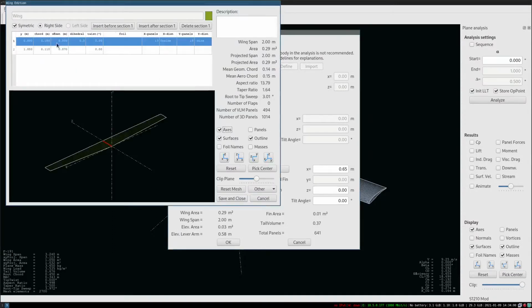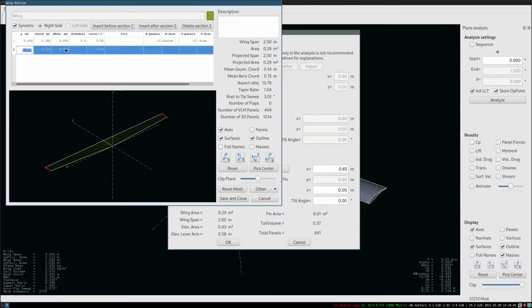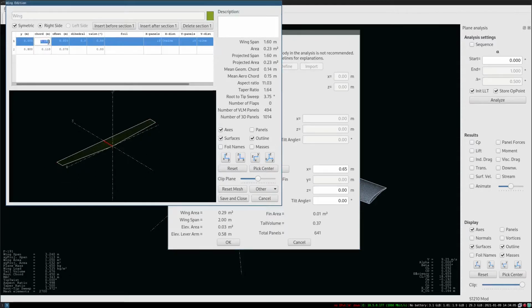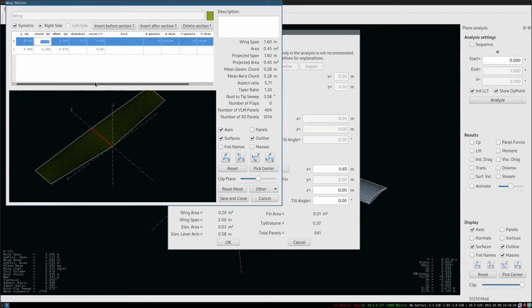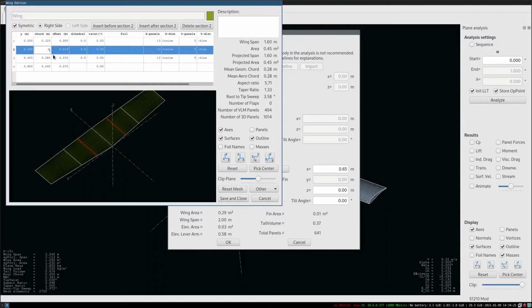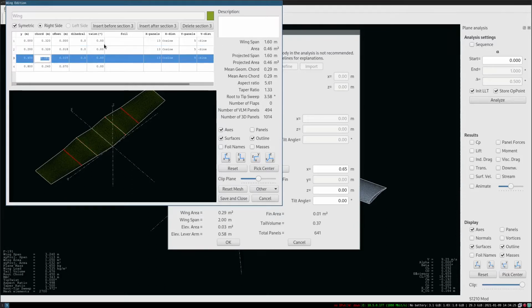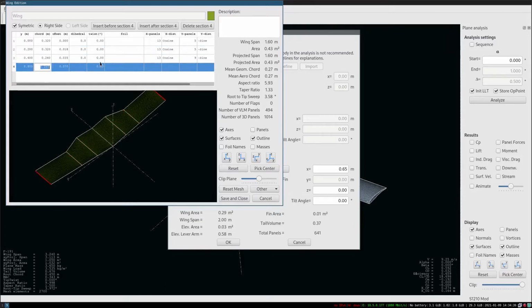We're going to have a look when we get our main wing together. In this case, we're probably going to set a 1.6 meter span. Let's go with a 0.32 to 0.24. That's not quite what I wanted. Something like that. Should be a bit chunky. Don't know, we'll insert a couple of sections in here. Let's do a 0.32 midsection, we'll taper that down to 0.24, and we'll go down again to 0.16 on the tips.